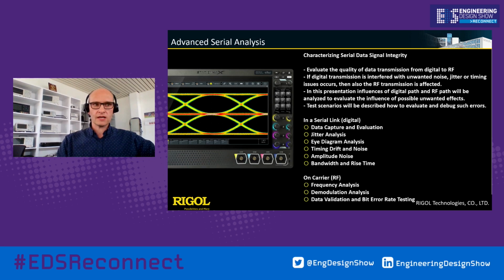The first part starts with the characterization of serial data signal integrity. So the first part is a description of the presentation, which is to evaluate the quality of the data transmission from digital to RF. Here it's quite important, when we make a design, to concentrate first on the data transmission on the digital boards and see some influences on the digital side like noise behaviors or interferences, jitter behaviors, timing effects, which then lead to a worse RF transmission in the end.